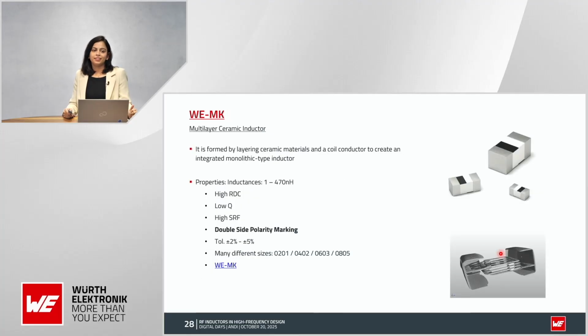Then comes the multilayer ceramic inductors. It is formed by layering ceramic materials and a coil conductor to create an integrated monolithic type inductor. What are its properties? High RDC, low Q, high SRF, double side polarity marking, comes with a tolerance of 2 and 5%, and many different sizes are available in this series as well.